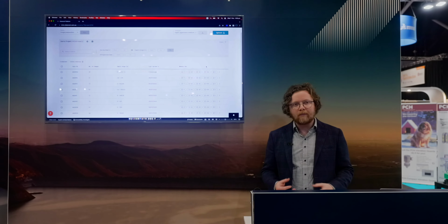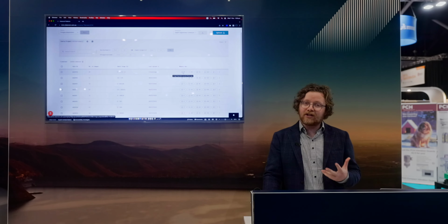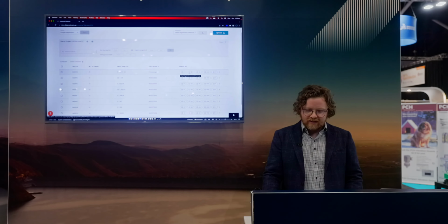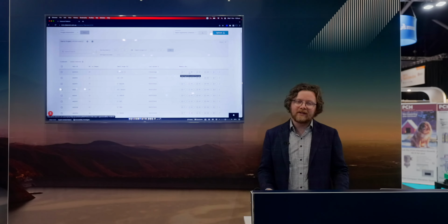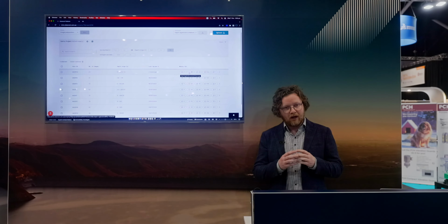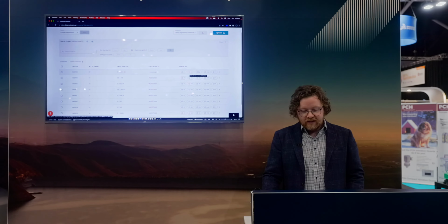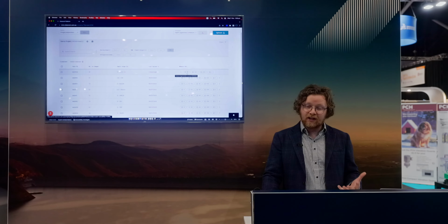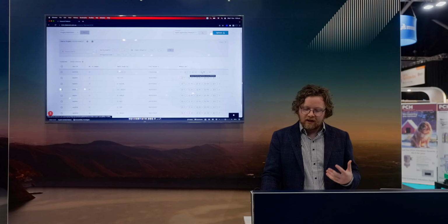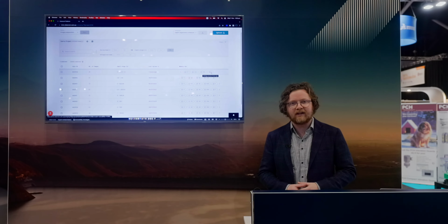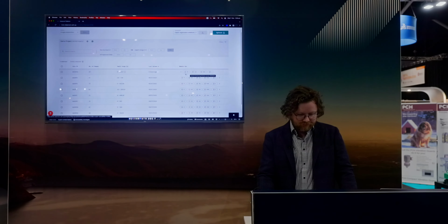So here we have IP, which stands for image preparation. It's the cropping of those raw core photographs. DR stands for depth registration. It's where we take those depth registered strips and we arrange them in depth space, using a process I'll explain in a moment. DB is the detection of drillers' break marks. We produce RQD, fracture frequency, fracture segmentation, joint set analysis, a geotech weathering intensity model, and a lithology model. So I'll show you a selection of these in the demonstration.